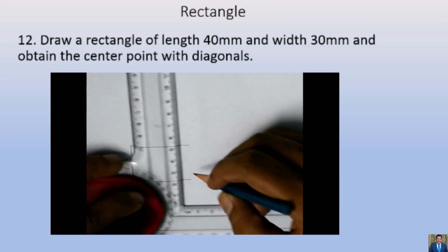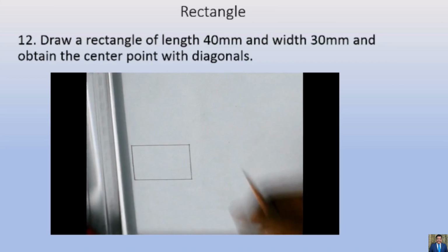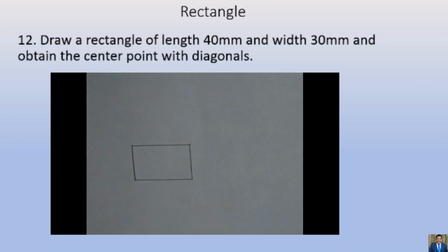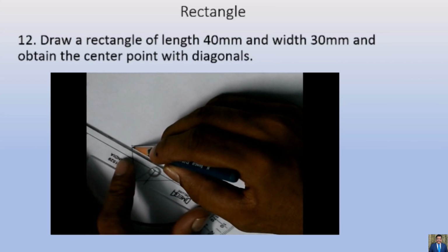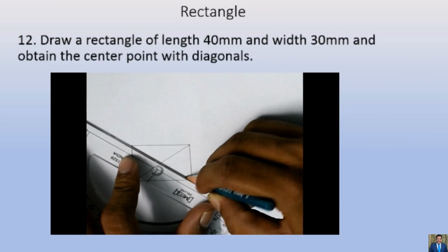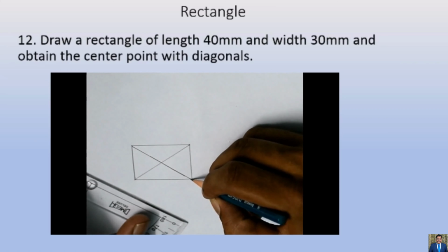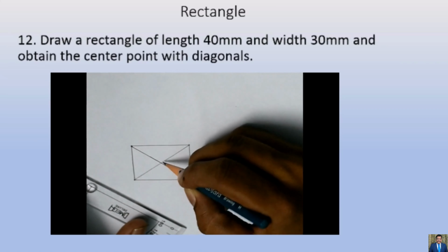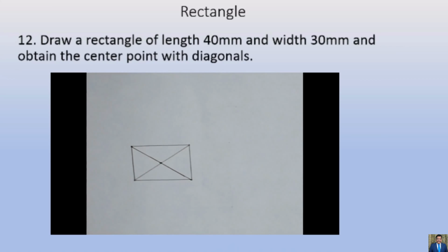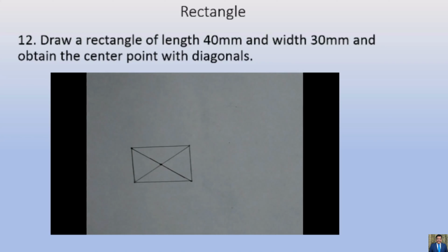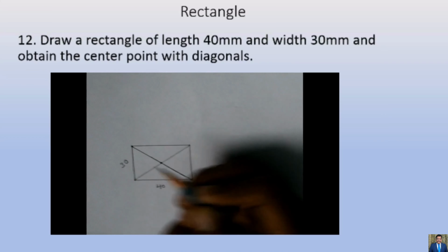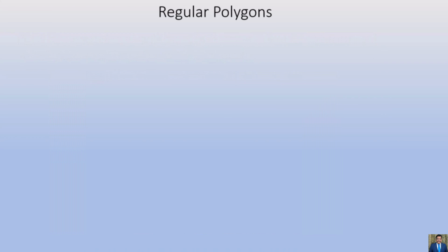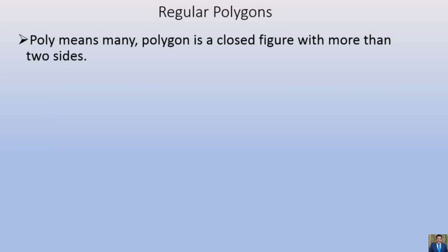So I can complete this rectangle very easily. So we can easily place the center point of this rectangle, but here it's best practice always to take diagonal lines to mark the center. As you can see here that by just drawing these two diagonal lines, I have got the center point here. And this is the easiest procedure to get the center point always. So I'll just dimension it. I am not dimensioning it properly. I'll do it later.